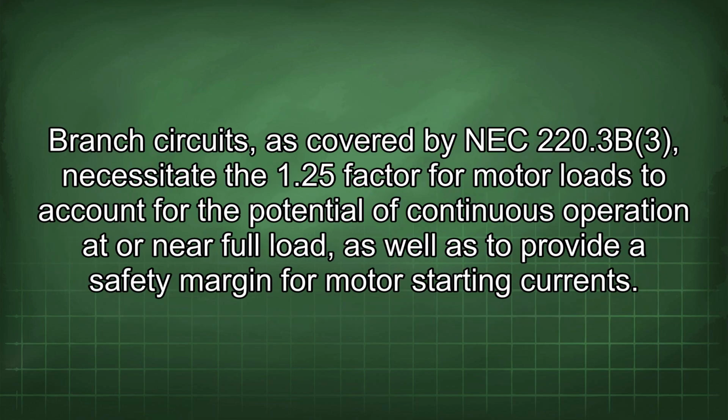Branch circuits, as covered by NEC 220.3B3, necessitate the 1.25 factor for motor loads to account for the potential of continuous operation at or near full load, as well as to provide a safety margin for motor starting currents.